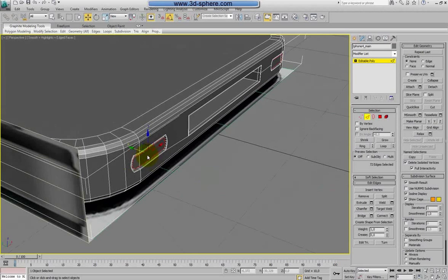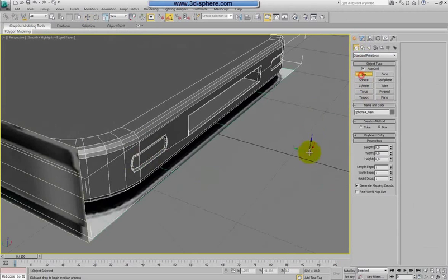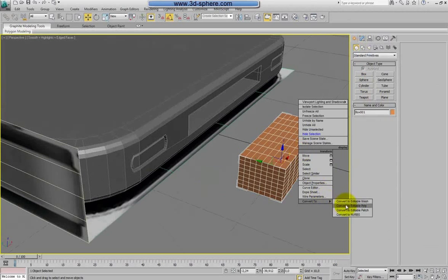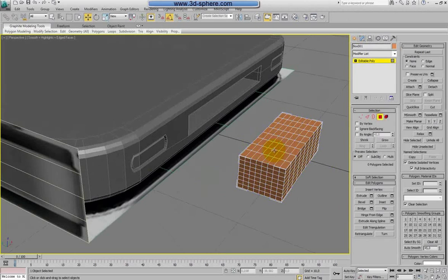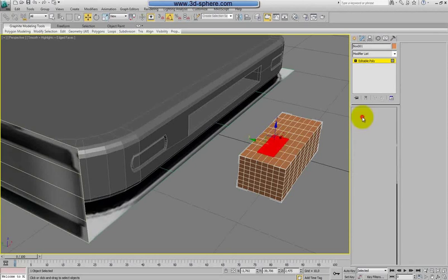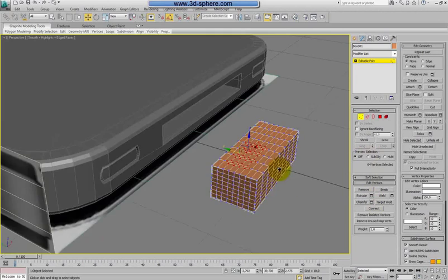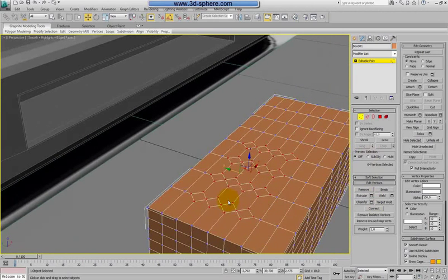It can be easily done by, like, I will show it very quick. When you do a box, let's keep this high 888, convert to poly, and let's select some polys, go to vertex and chamfer them, not so much of course, like this. So we'll have the initial shape from which you can start to do the grid.